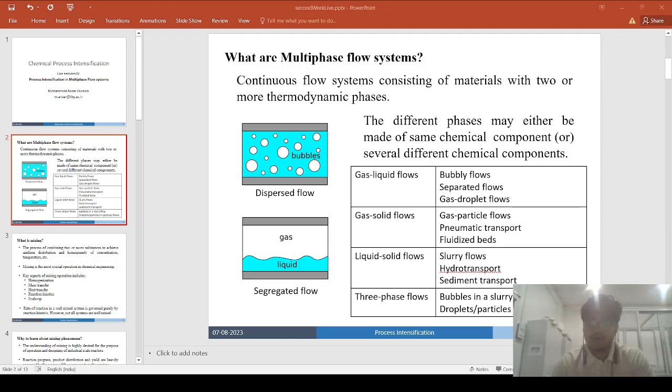And rotating disc packed bed systems, a multi-phase system, generally perform well. So for the rotating disc system that we have discussed in the previous session, rotating on the centrifugal distillation tower, what about if you involve a packed bed also? That results in better mass transfer of mixed liquid and gas phases, and you would get a very high interfacial surface area, in a counter current fashion.